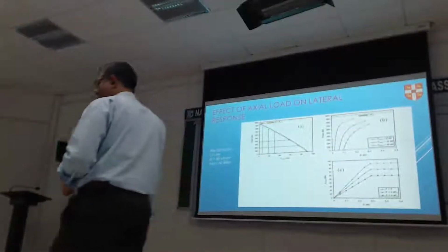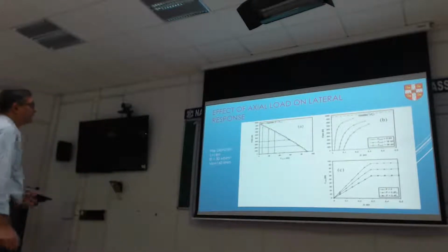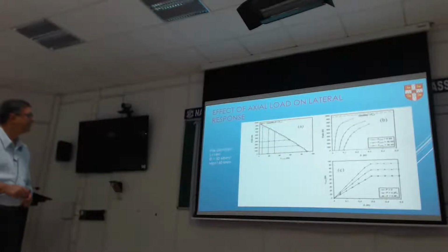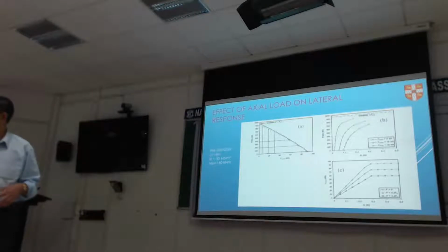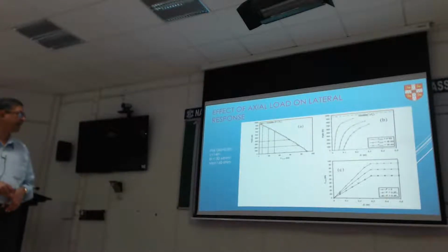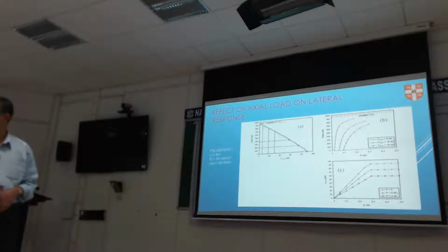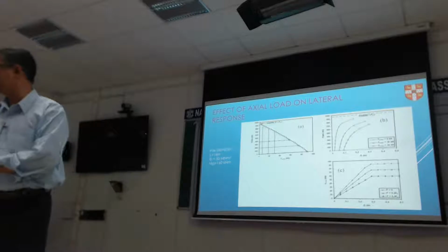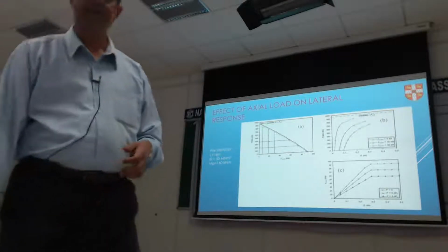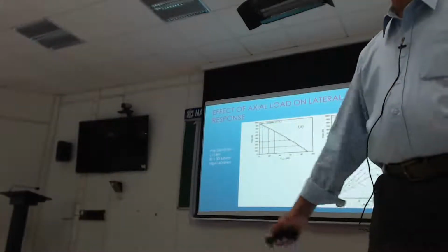Either it change in the curve shape and the type of the point. At graph C. C below. Oh, this one. Oh, this is because you're getting to the buckling limit. So this is the elastic weight, and that's the buckling weight. So that's why it's thinking that. So you haven't got any more to go by. You are on the cusp of yield. It's like an interaction curve. Yeah, basically. That's the name for it. I didn't use the name, but yeah.